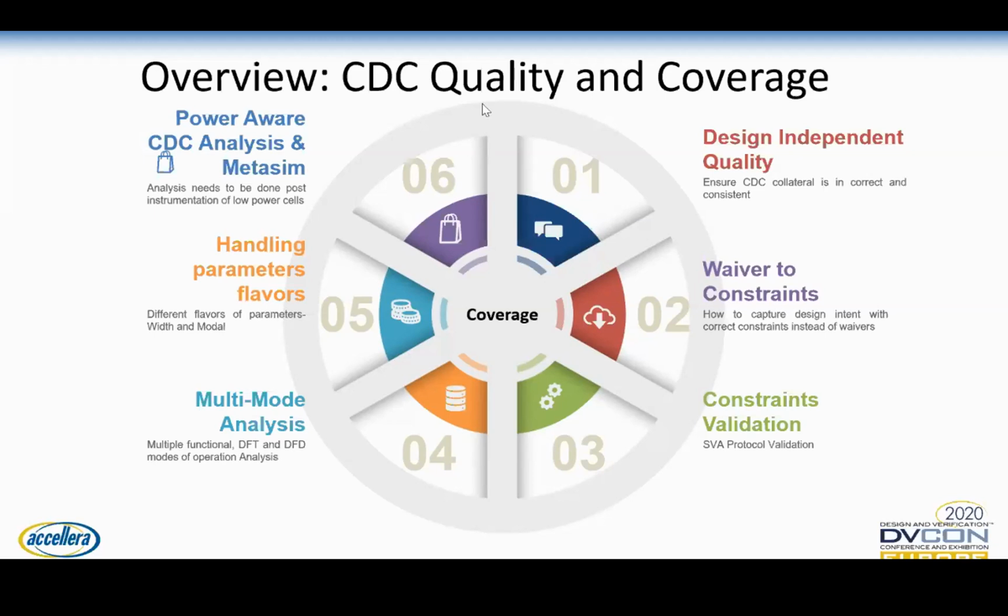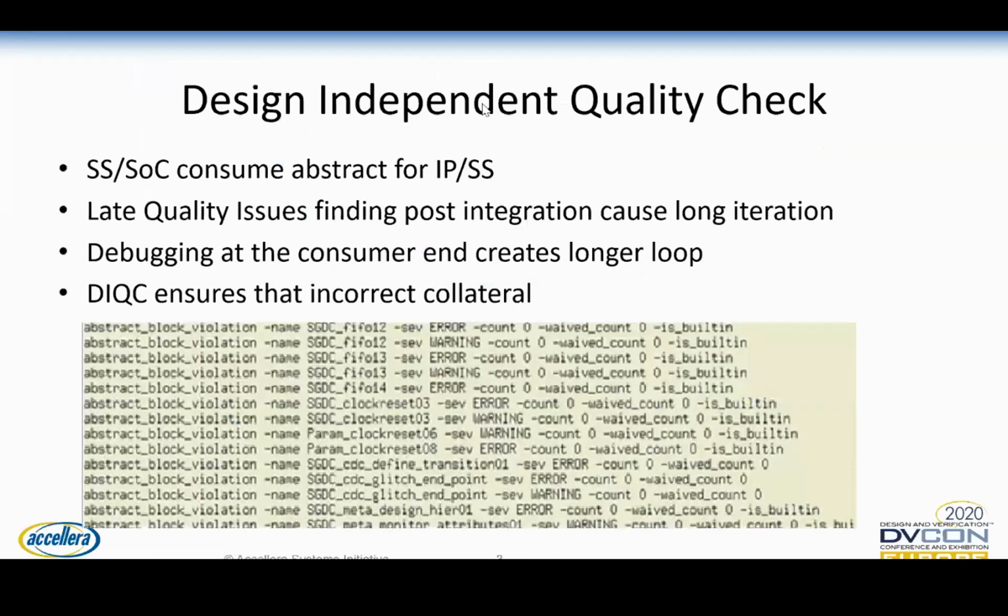And also the metasim, right? We also do the validation domain, that random delay simulation, wherein we assume some of the cycles and we inject the fault, right? And we see whether the output of the deterministic model is actually with glitches or unstable or not, right?